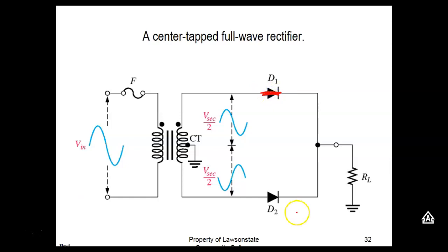So this diode is going to be on all the time. When this goes positive, this one right here turns on. It comes through here, this cycle, that's a straight piece of wire, and it comes back here and we have a short circuit. So in a full wave bridge, center tapped, if one of your diodes shorts, you get a short circuit, and hopefully it will blow this fuse right here. We try to fuse the primary. If we use one fuse, we try to fuse the primary because it protects both sides of the transformer.